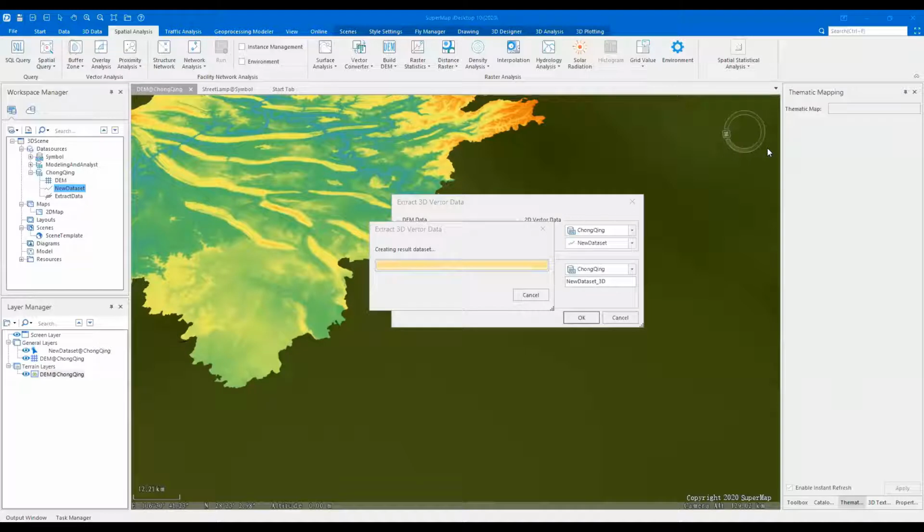The first is the elevation scaling factor. This value refers to the unit conversion factor of the grid value, which includes the z coordinates, that is the elevation value, relative to the x and y coordinates in the DEM grid. Usually in calculations where x, y, and z are all involved, it is necessary to multiply the elevation value by an elevation scaling factor to make these three units consistent.